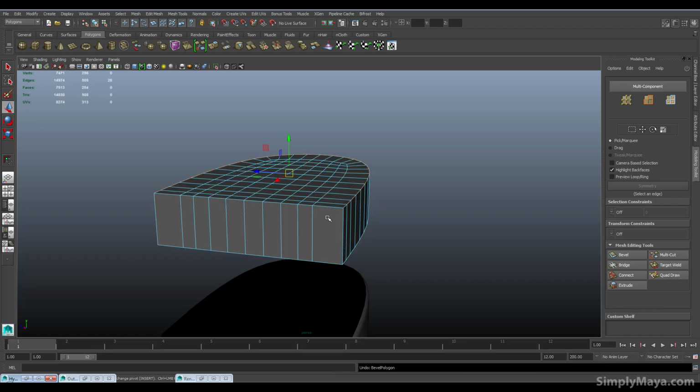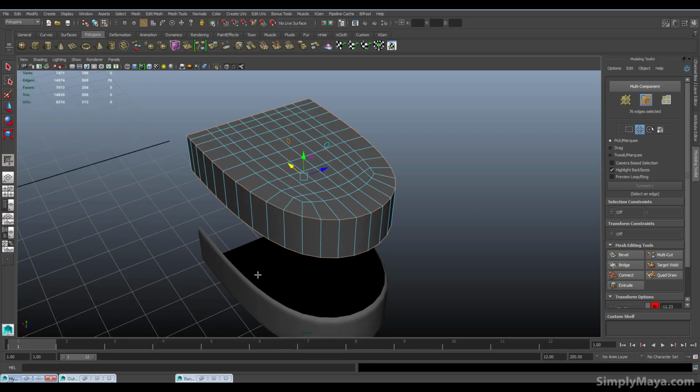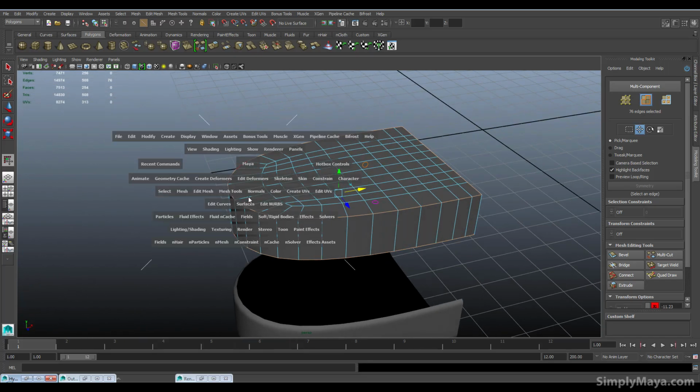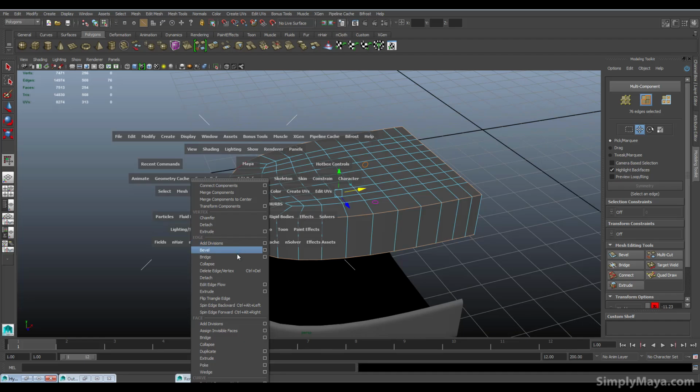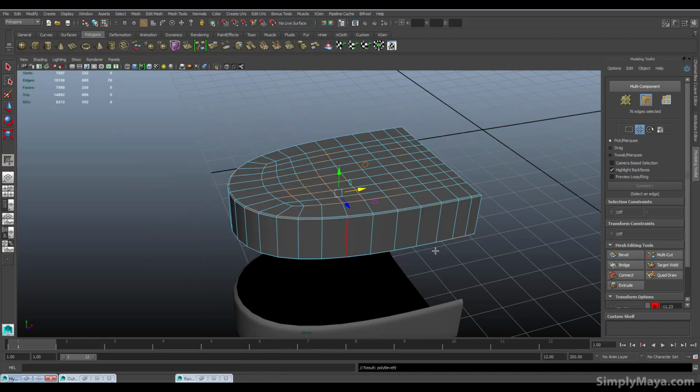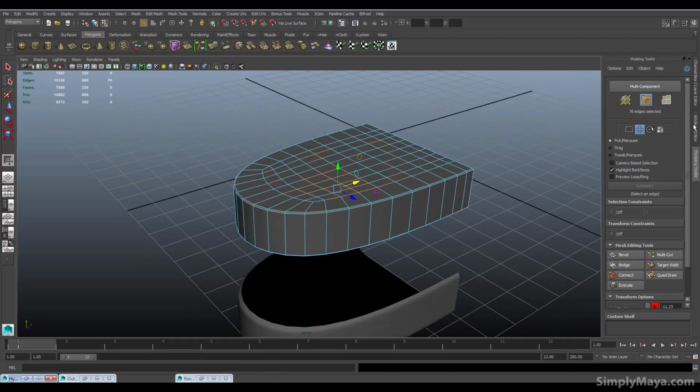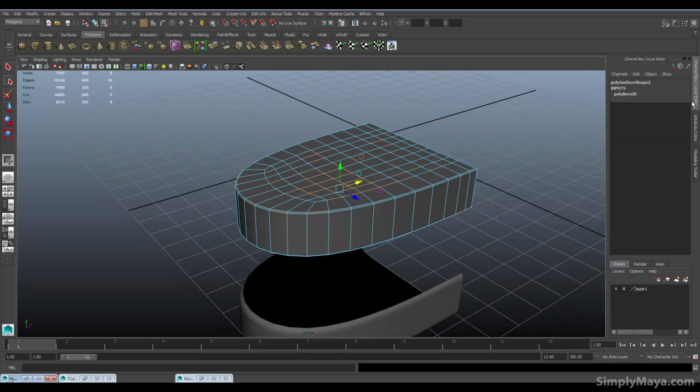In our case, of course, I want a bevel around the whole thing, so let's just select edges 1, 2, 3 and 4, and bevel. Okay, now I can increase the size of that because we went to all this trouble to get it, so let's increase the size and maybe a fraction of 0.4. There, done.